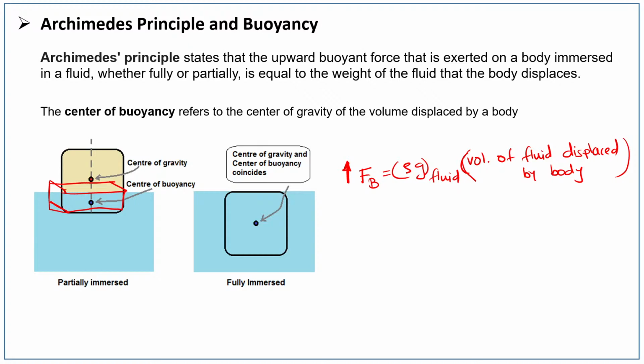Center of buoyancy, you can see, in these two cases will be different. The center of buoyancy is where the buoyancy force will act, or in other words, the center of gravity of the displaced volume. Whatever volume is displaced by this body, the center of gravity of that displaced volume is nothing but the center of buoyancy. In case of a floating body, this is the center of buoyancy. In case of a fully immersed body, the center of gravity and center of buoyancy will coincide.